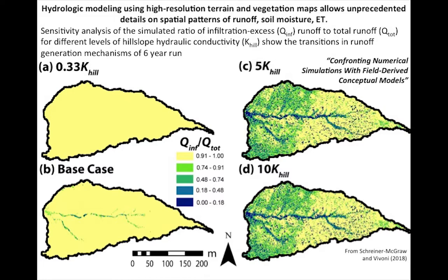By setting up the model with topography, vegetation, and a 1 meter Voronoi mesh defining the top of the soil prisms, they could solve the full hydrologic problem, exploring the changing conductivity of the hillslopes and the trade-off between runoff generated directly from the hillslopes or following percolation.